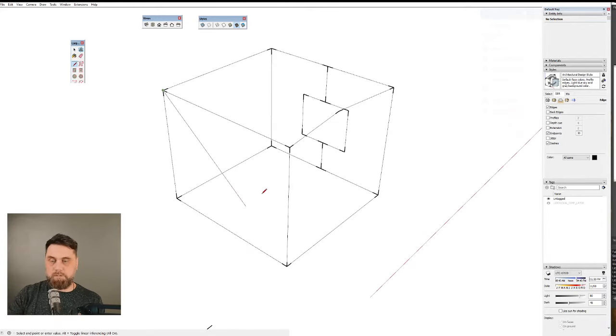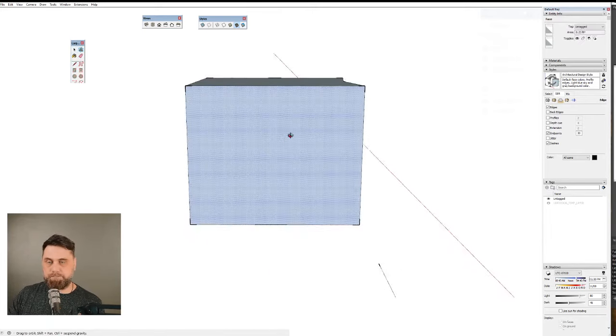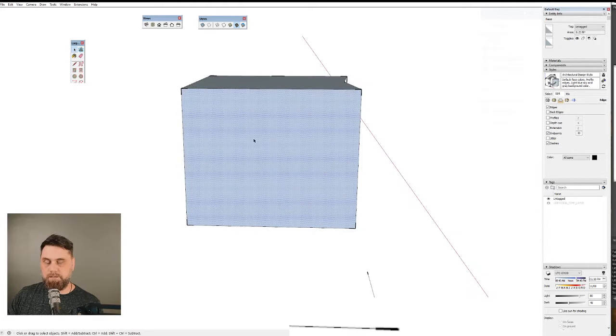But first you need to have that frame. Now, in SketchUp, if you make a complete circuit and you close the frame all the way around, it will give you a face. So you get a face here.